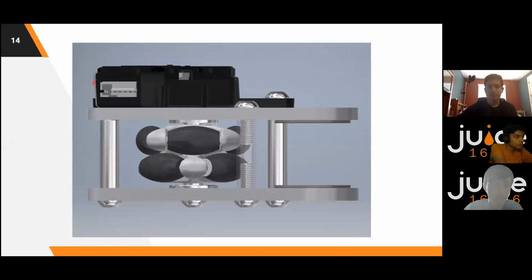I actually designed this one a few weeks ago, because I wanted to make it smaller for our next year's robot. You can see here we have that aluminum shaft going through the omni wheel and into the encoder, and it's important to use bearings, because you want this system to have very little resistance, so you pick up all those small changes in position.